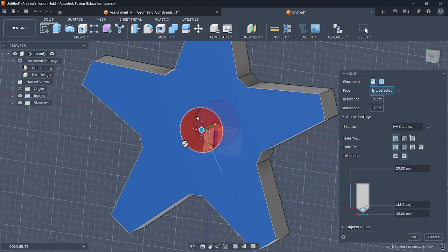But you can see here, there's a bunch of different options, right? And this can be very convenient when you're making certain parts, because you might want to countersink or counterbore. And it'll do all of this in one operation while retaining more information, right? This gives you information on the depth, even the angle of the drill bit, if that's important to whatever you're making, and then obviously the diameter as well. In our case, we're going to make a tapped hole, so I'm selecting this.